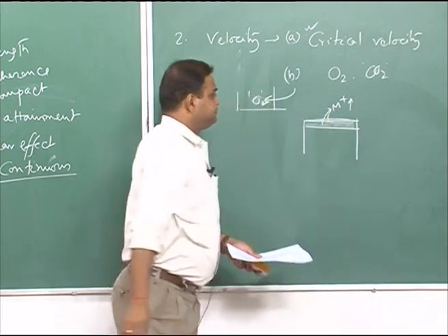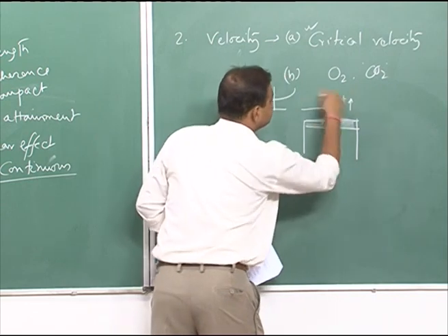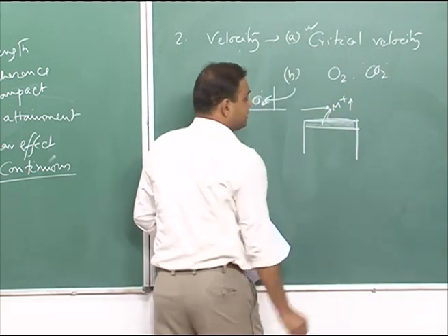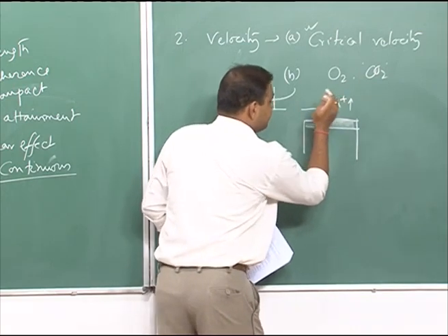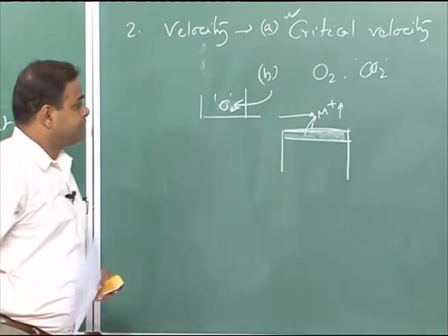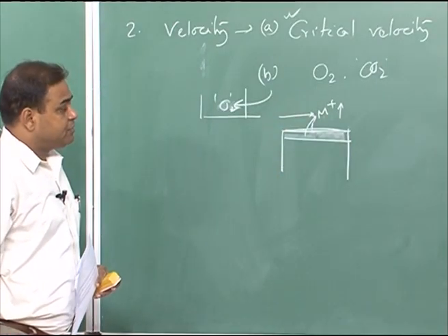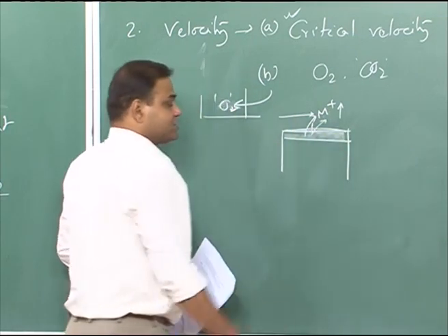and the passive film will grow. But if somehow I drive away all those metal ions that are forming on this metal surface, which are in equilibrium with the passive layer and the solution, and we break the equilibrium, then more and more metal ions should come in order to maintain that solubility.